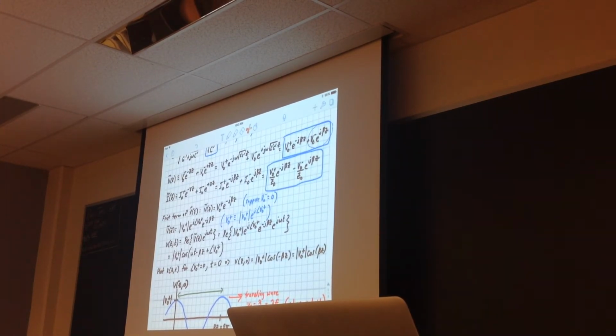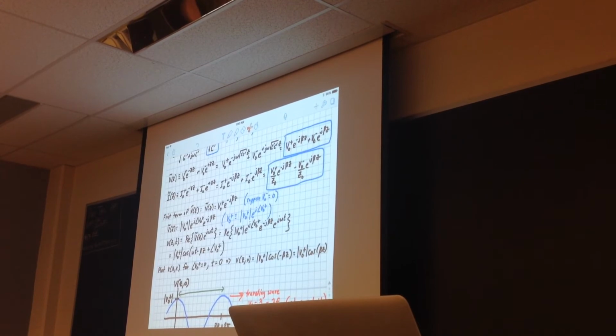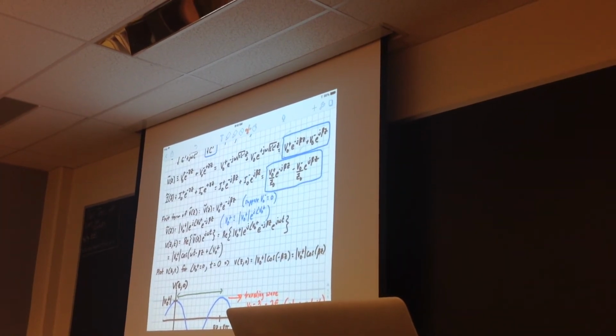So it's got a constant and it's got a different sign in the exponential. We got V0 minus, that's a constant, and e to the plus j beta z. Someone, from what we just learned, physically, if this is a traveling wave as we just described, what might that term there represent?